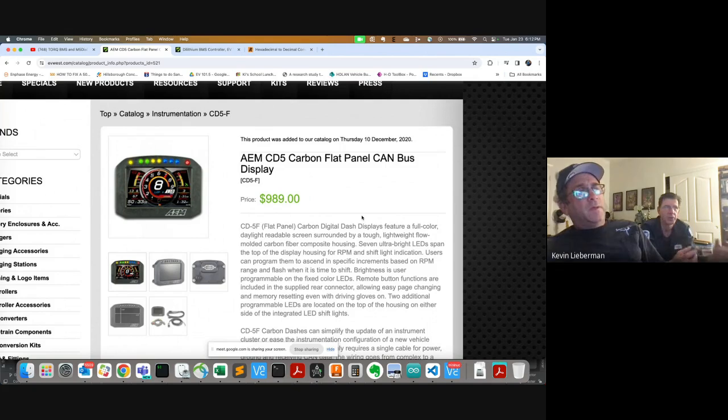Yeah. Or like a cell tap, it would say, unplug cell tap from module 5. And then it might show you a picture of where module 5 is, and then the students would go into the battery pack, unplug that one, and then you would see the actual voltage value change. Right, because you're causing a fault, basically.